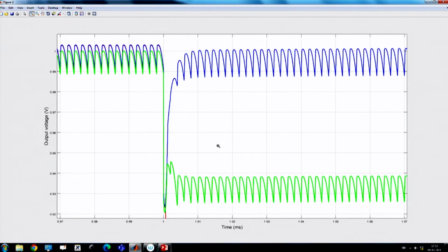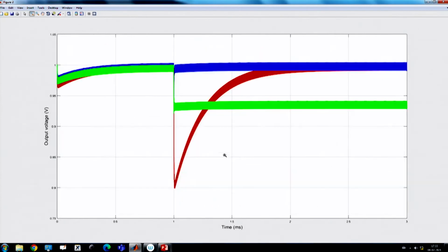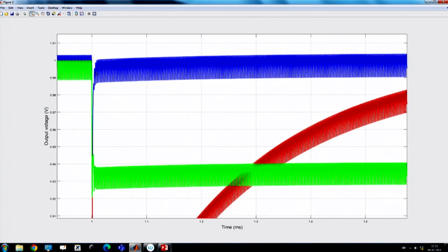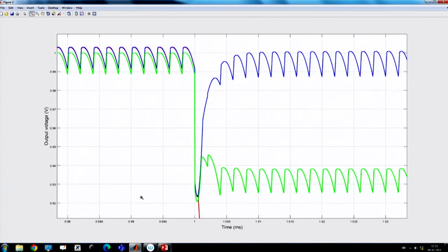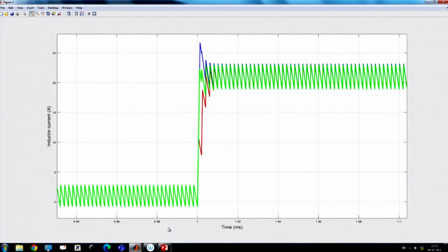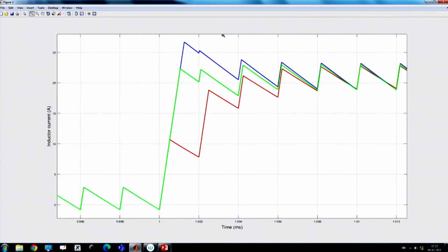We are emulating that we are introducing a DC output impedance which is the same as the ESR of the capacitor, and if you do that, we can get the output impedance almost independent of frequency, because it does not actually seem to have any transient effect. Okay? And if you go to the current waveform, the current simply keeps going there and staying there, no overshoot is there. And another thing is that there is no current overshoot. That is the beautiful thing.